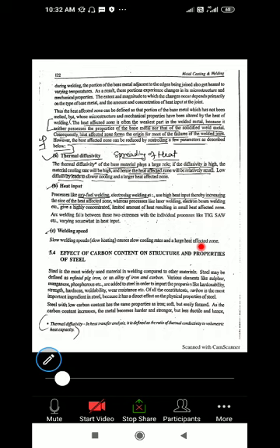The heat affected zone is often the weakest part in the weld metal because it neither possesses the property of the base metal nor that of a solidified weld metal. Now listen carefully. The heat affected zone is often the weakest part of the metal because the weld portion is there, where the welding is, it is the stronger one. From that weld portion the surrounding part is the weakest part. Why is it called the weakest part?